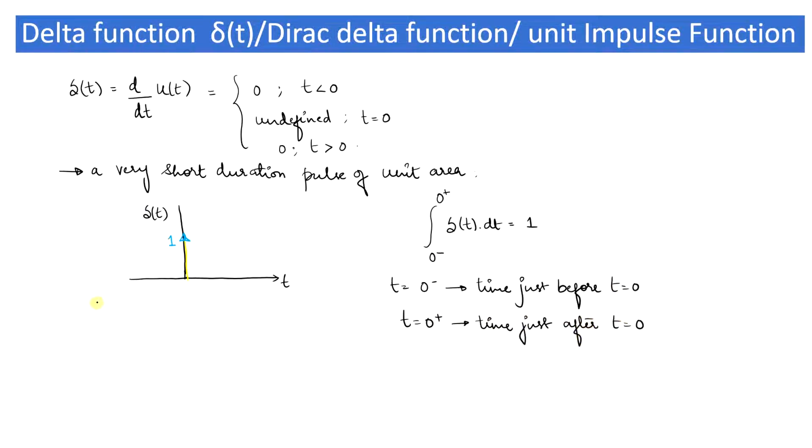The area under the pulse that you can see is equal to 1, so you have to ensure that whenever you draw the signal, you specify the magnitude 1 beside the arrow, so that it's very clear that you have marked the delta function. Okay. Moreover, this magnitude value equal to 1 basically indicates the strength or the weight of